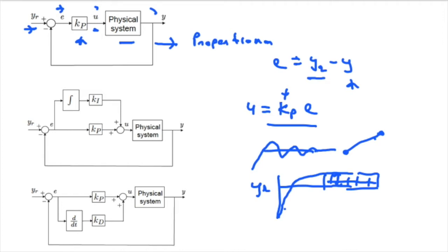So what integral control basically does is apply control proportional to that accumulated error. Okay, so the objective of integral control is basically to get rid of steady state errors. And we will see that integral control generally increases the order of the system, because if you take the Laplace of this, it will be 1 by s. So 1 by s, when you add it in the denominator, the order of the system increases, and that sometimes is not good. So we will give you some techniques, like if you are doing inner loop control and there is no steady state error, it's not a good idea to apply integral control.